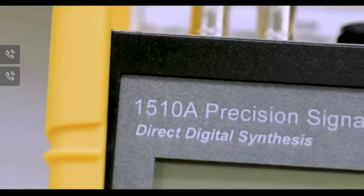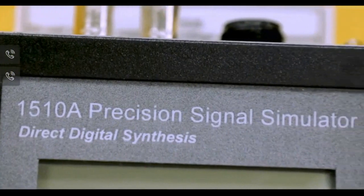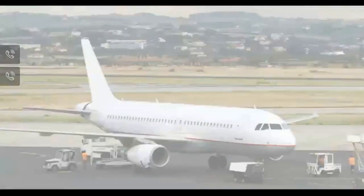So you can actually use this to calibrate your signal conditioning equipment, whether it's an accelerometer or an eddy current. You can create various different signals that simulate those sensors to verify that your signal conditioning equipment is working. And this stuff can be out in the field where there's no external power source around that you could typically plug a standard signal generator into to simulate this. The 1510A, because it's battery operated, can be used out in the field or pretty much anywhere. It can be used in an airplane up in the air without having to connect to an external power source.